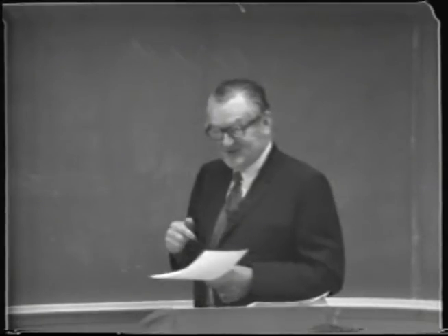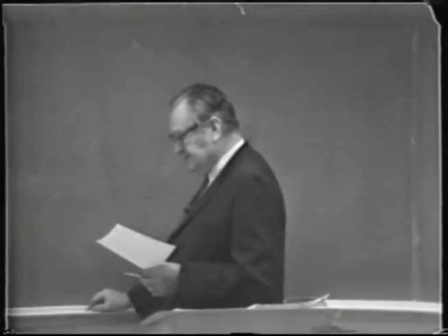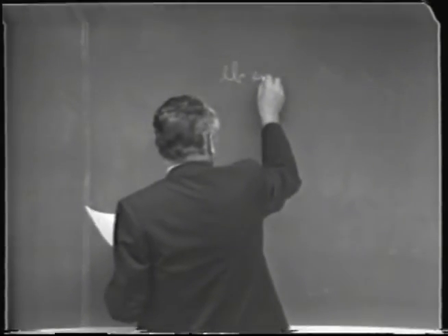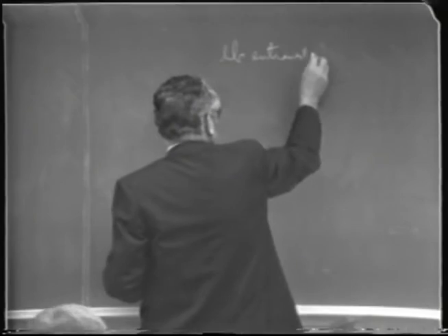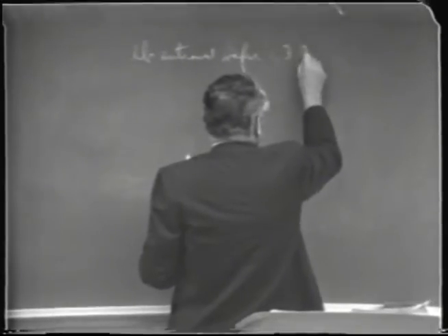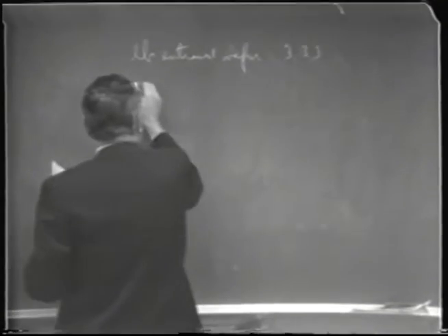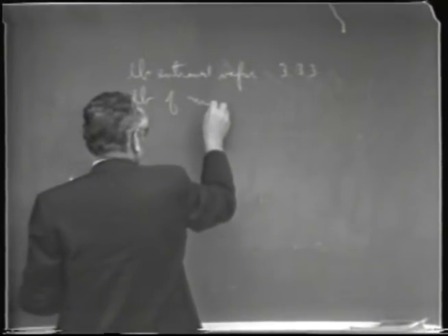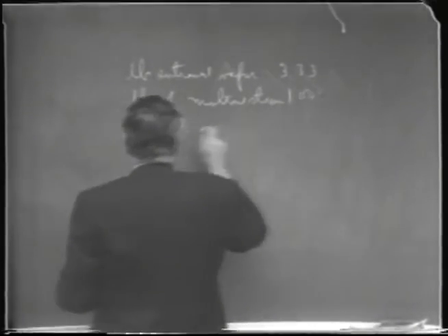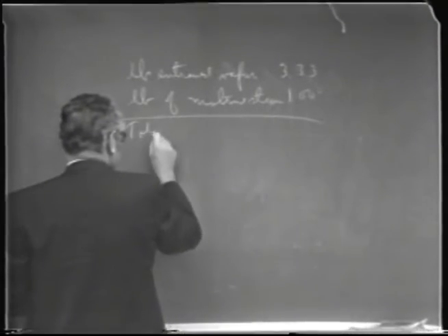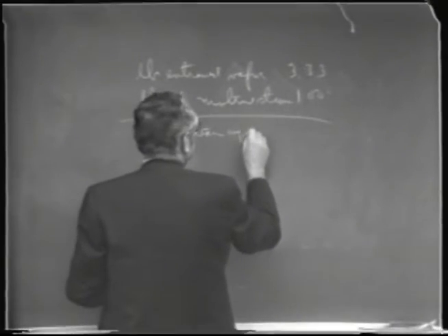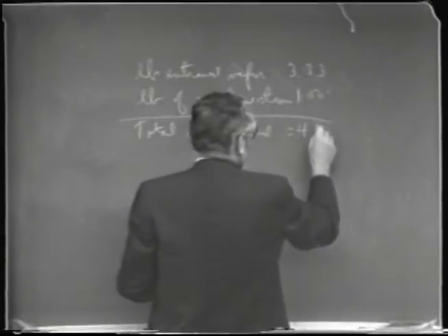In other words, the way you get that percent saving would be that pounds of entrained vapor is equal to 3.33 per pound of motive steam, so the total steam required is the sum of the two, 4.33.